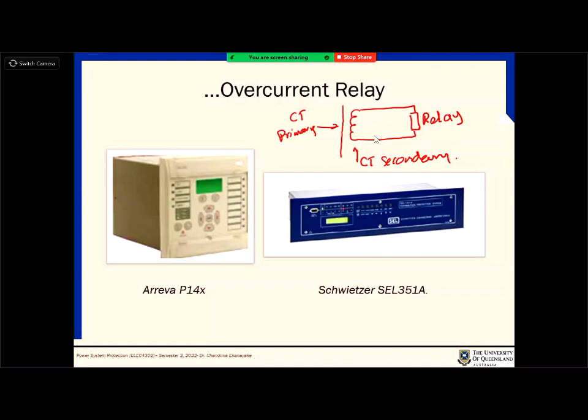That's why, when the relay terminals are open, it means that you have a very high impedance across it, right? Very high impedance. Now, if the CT cannot work with that sort of impedance, then what we do is that we reduce the impedance level. When it comes down to a certain level, then the relay can work without any problem.